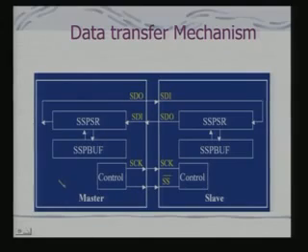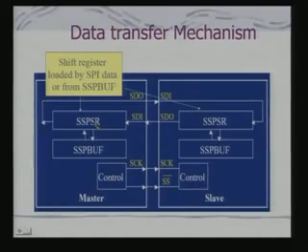Again, these registers are involved. This SSP buff register we have already seen earlier in the context of I2C, the same registers are involved, and this is a control logic which would generate the clock, and it has to also generate the slave select signal. What we have got here is SSPSR, a shift register. SSP buff was a buffer register and it is not a shift register.